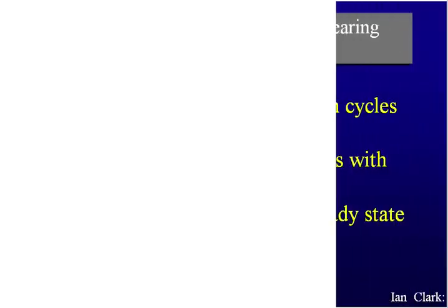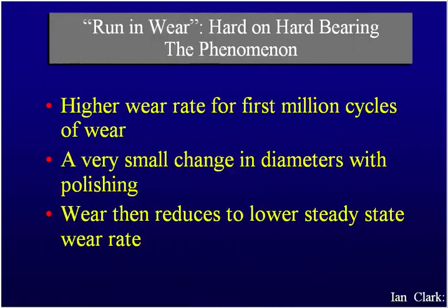Run-in wear is a phenomenon that you need to know. It is on a hard-on-hard bearing. It's been seen with metal-metal as well as ceramic. What happens is you put these two bearings together and you run them in for a while. It's just like your new car engine with the pistons. You get a high wear rate for the first million cycles, and then you settle down to this equilibrium where you have